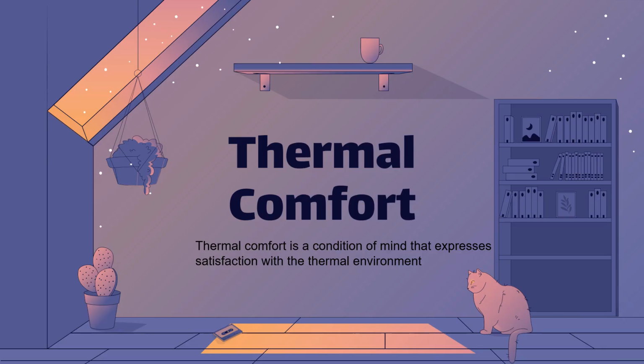Next, I will be explaining about thermal comfort. Thermal comfort is a condition of mind that expresses satisfaction with the thermal environment. Due to its subjectivity, thermal comfort is different for every individual. These factors may be independent of each other but together contribute to the occupant's thermal comfort. For example, air temperature, radiant temperature, air velocity, humidity, and for the personal factors, clothing and metabolic heat.